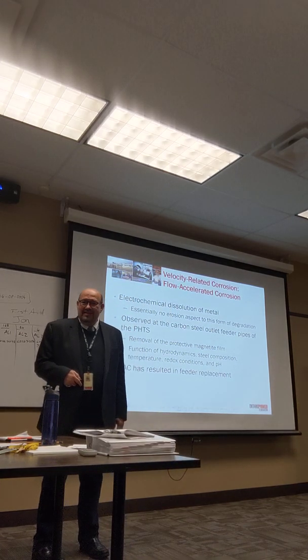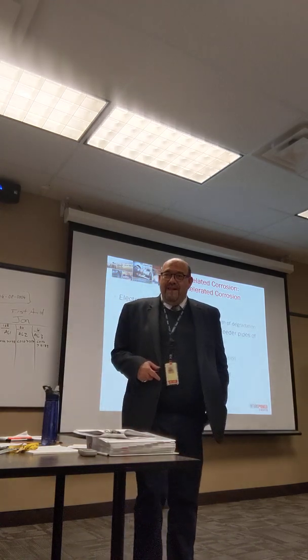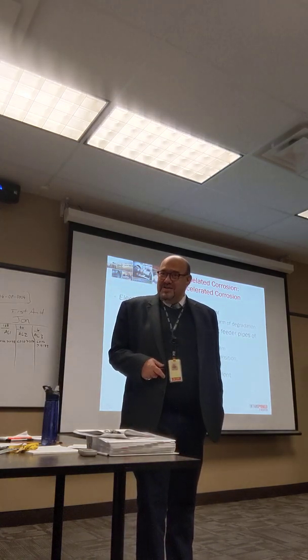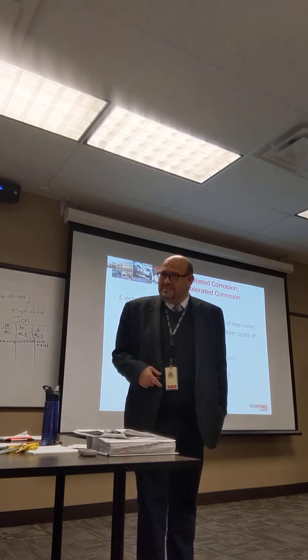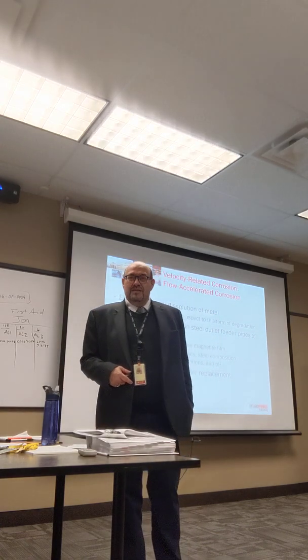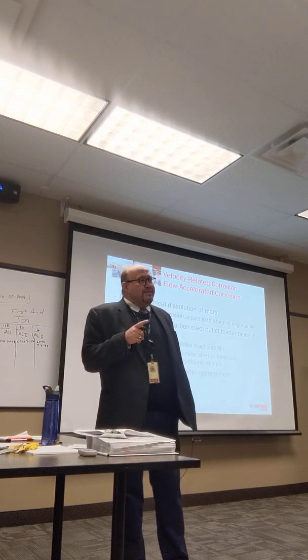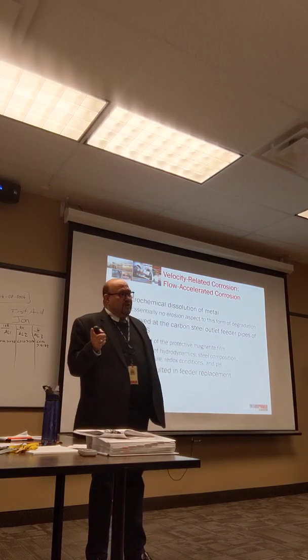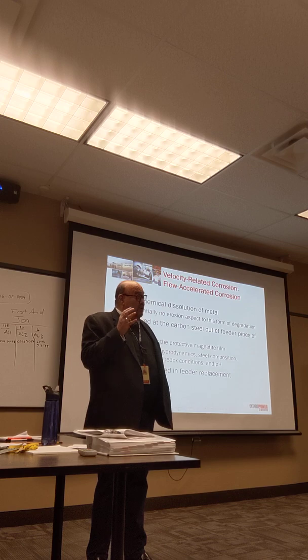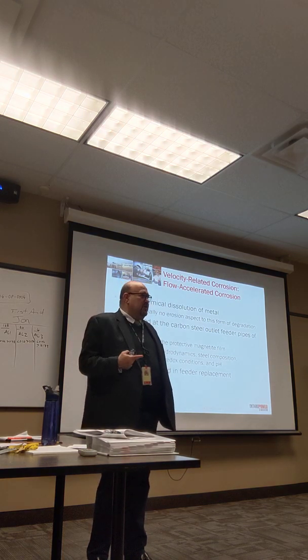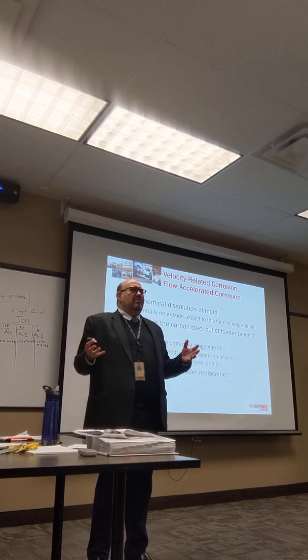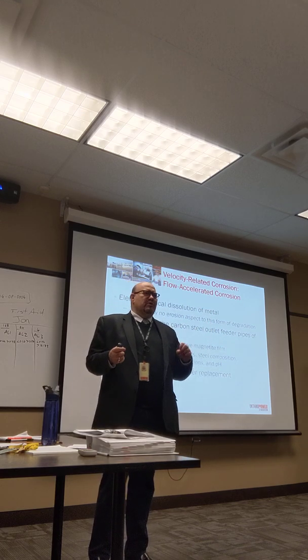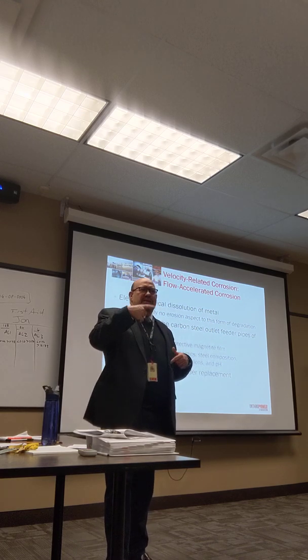So that will be a hot conditioning for making the protective passivated layer. That's coming up with the hydrazine addition, those things for Unit 2 before startup. The chemistry is a very involved process, and sometimes you're doing things for years, and then it comes and they say, now we have to condition for something, now we have to accommodate the new design.